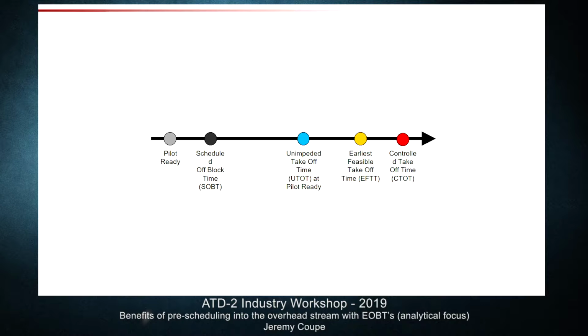Ultimately, this earliest feasible takeoff time prediction is passed to TBFM, and TBFM uses that as an input to generate what we call the controlled takeoff time. The controlled takeoff time is that ultimate time that aircraft should comply to merge into the overhead stream.